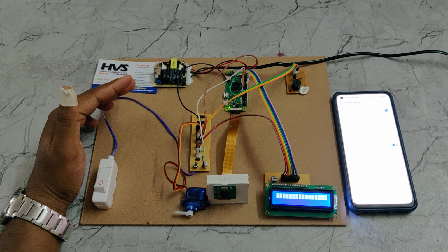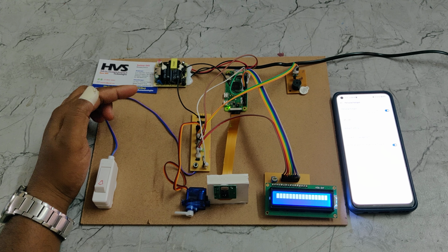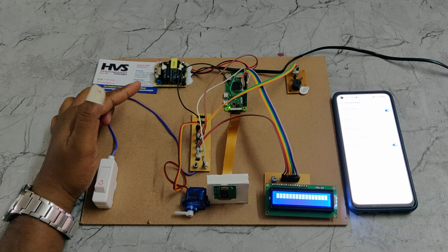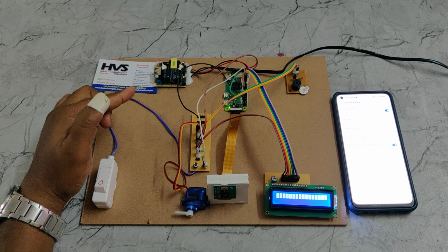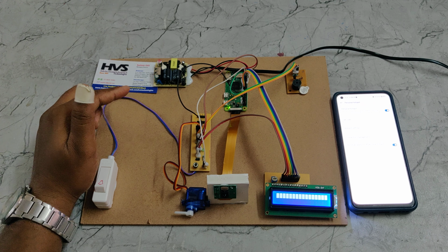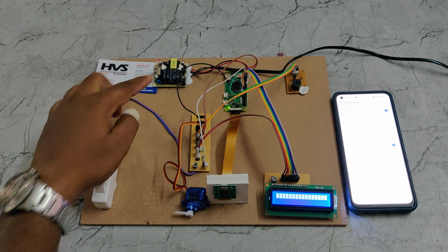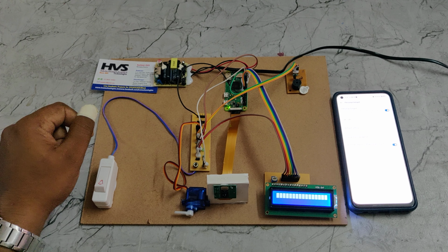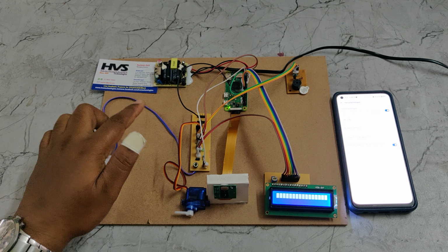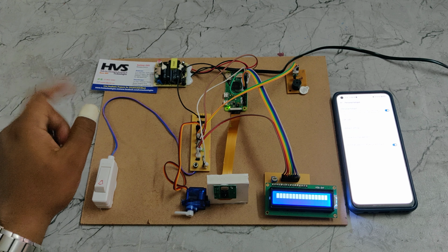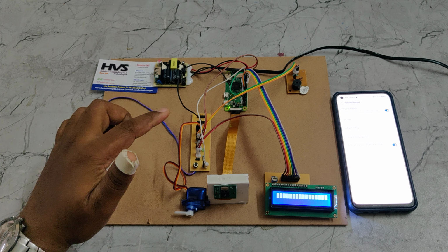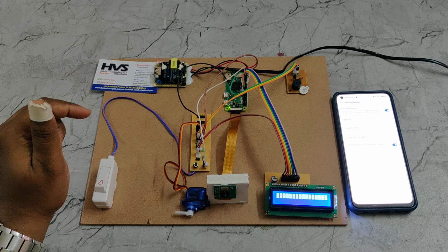Coming to this regulated power supply board, it has 4 stages, which take 230 volts AC input and provide a 5 volts DC output. The stages are: a transformer to step down the 230 volts AC to 12 volts AC, a rectifier to convert the AC to pulsating DC, filters to remove the pulses and make pure 12 volts DC, and a regulator which takes the 12 volts DC input and provides a constant 5 volts DC output. When we provide that, the system will start booting into the operating system.